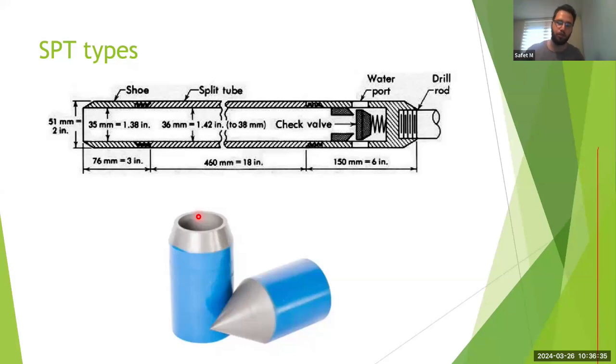What you're usually doing, you would divide your rod into 3 times 15 centimeter scales. You would count the number of blows for each. For soft soil, it would be 3 or 4, something like that, and for really stiff soils it would be 40 to 50.